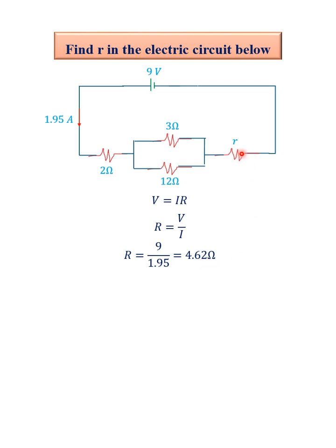However, the sum of the resistances is not the algebraic sum because resistors don't add up that way. First, we need to understand the connection of the resistances, whether they are in series or in parallel. The first one we've identified here, the obvious one, is that the 3 ohm resistor is in parallel to the 12 ohm resistor.